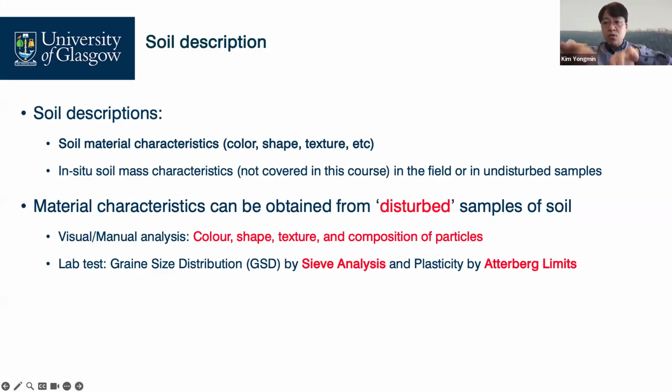We have so much soil out there, and we bring it to our lab and then classify. Oh, this is sand, this is clay, high plasticity, low plasticity, gravel, sand, silty sand. We form groups, and the soils in a specific group show similar engineering behavior. That's why we have to classify our soils, to better understand them.